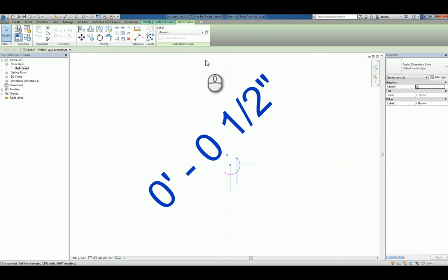You'll notice also in Revit 2017, the label parameter feature is no longer in the Options toolbar. It's up here in the Contextual tab. You'll also notice that if you click the drop-down list, it's going to give you a list of the ones that already exist and the ability to search. You have to click the Create Parameter icon here to create a new one where it used to be down below here in this drop-down list.